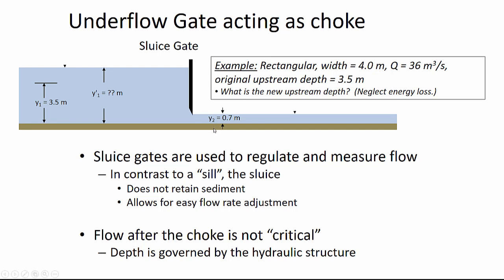What we're saying is we want to find out what is the energy required at 2, and is that same amount of energy available at 1 without pooling? I think we'll find that there isn't. And so therefore, what we're going to look for is there's a certain amount of energy that has to be existing at 2, and so what depth of accumulation upstream is going to cause that energy. So E2 is going to equal E prime 1.